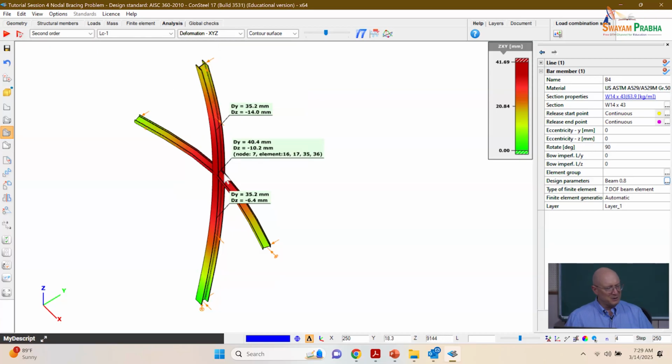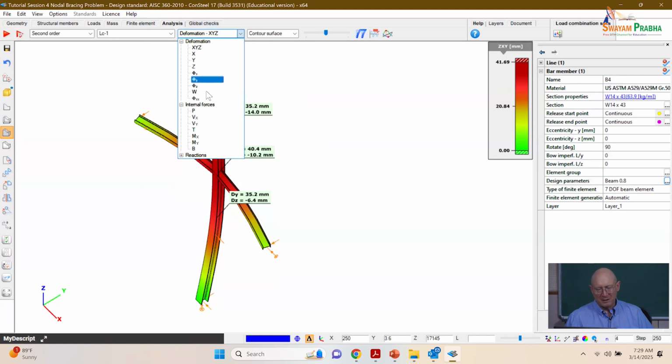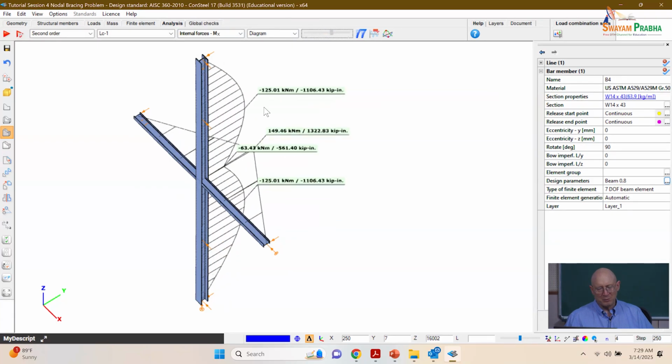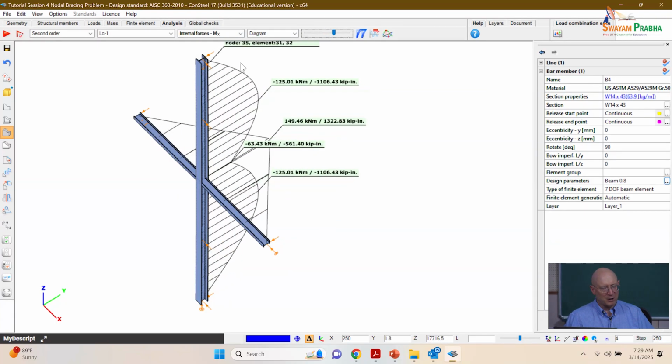If it is braced sufficiently, you may have the largest moments in the column based on what we've got here and the moments in this problem. These are second order moments. But we would also need to check whether the column is still working if the imperfection is an S shape.